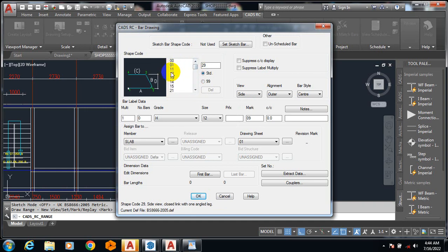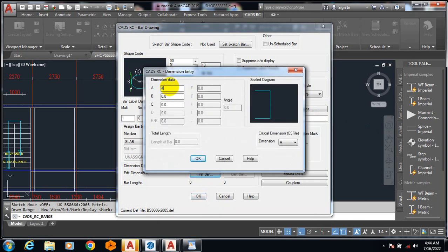Now we are going to do a slab detailing. I'm going to start with this, and my reinforcement is a bottom bar. I'm using a slab thickness of 150. Then if I click on Fix First Bar, I can come here and type the length of this bar. I'm just going to give it a particular length, let's say 5 meters. I'm going to show you how to stretch it to make it fit exactly the way it should, but right now I'm just typing a value.